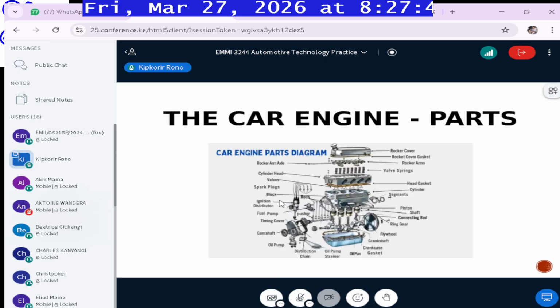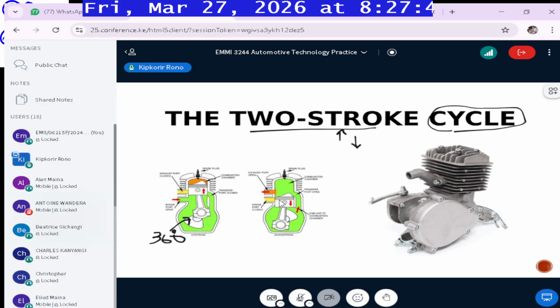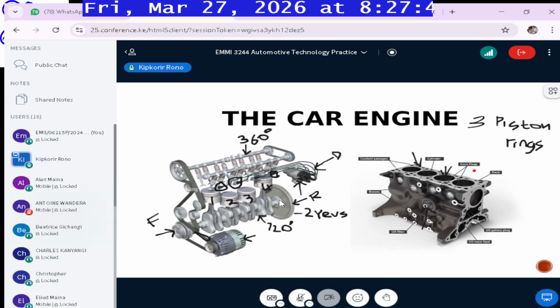Okay, because in the engine block, if you see this image here, in the engine block, I don't know whether I can be able to show this. You can see that there are small holes in the engine block like these. So these holes, these ones here, these holes you see in the engine block, they are coolant jackets. So they allow coolant to go into the engine block. So the engine block is not like a solid mass. Okay, they usually have channels inside that allow the coolant to go in and come out and move around and all that.